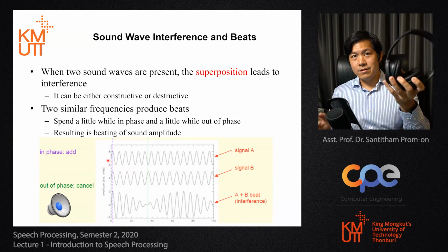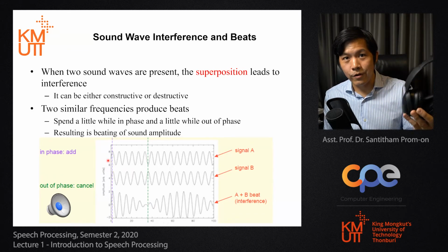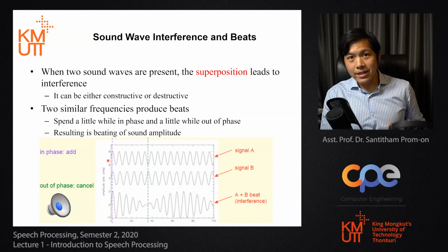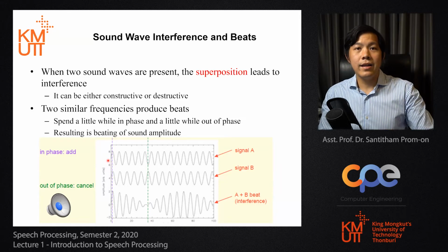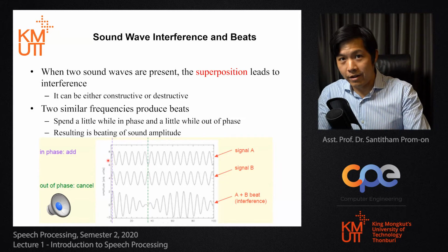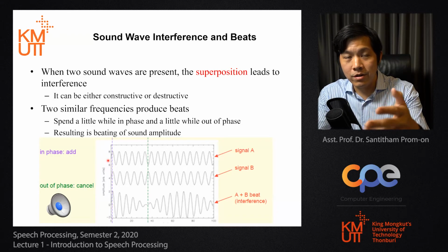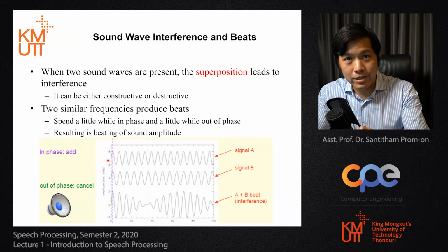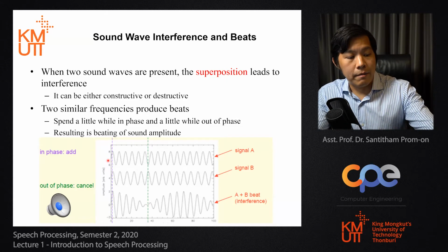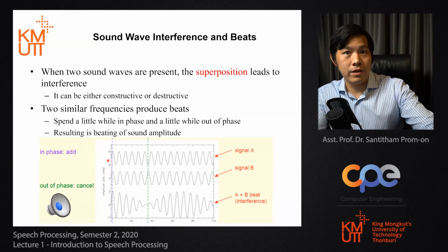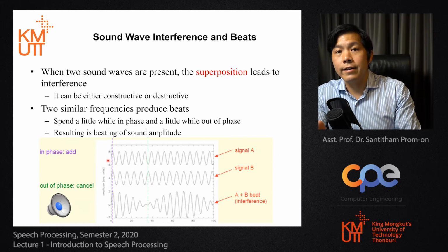Ta-da. The noise cancellation headphone. Right. Active noise cancellation uses this property. It creates the out of phase version of the noise to subtract it out of the actual speech, actual voice data. By having a microphone, it perceives the noise and then uses that noise to subtract out the actual noise that occurs.